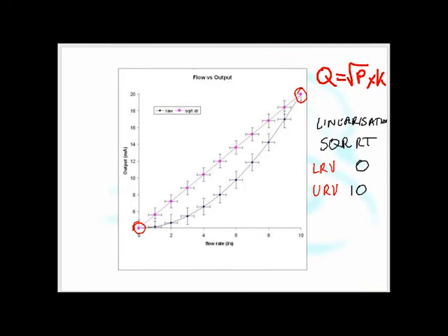It might not be until years down the line that someone realizes that when my flow meter is saying that it's 12 milliamps, for instance, 12 milliamps is mid-flow, my flow meter, when it's giving out 12 milliamps, will be saying that it's 5 liters a minute. But the real flow will correspond to the other line.